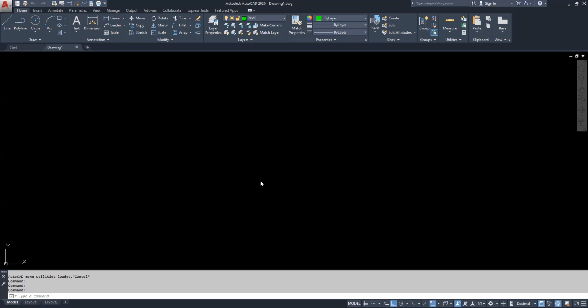With these drawings, you're going to want to read the top directions. Start a new drawing called ratchet. Keep the default units set to decimal units, but change the number of decimal places past the 0 from 4 to 2. So you want to type units at the command line.